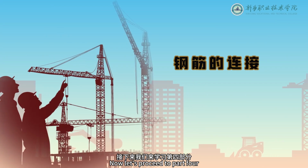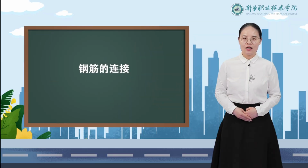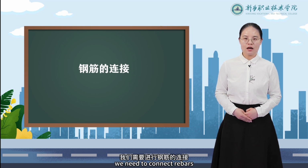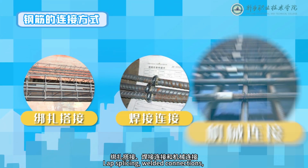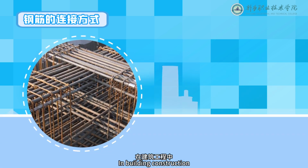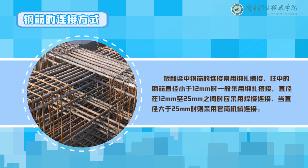Now let's proceed to Part 4, rebar connections. In construction, when rebar length is insufficient, we need to connect rebars. There are three connection methods: lap splicing, welded connections, and mechanical connections. In building construction, slabs and beams commonly use lap splicing.